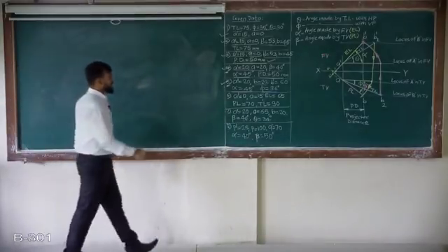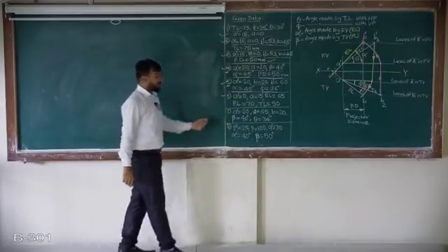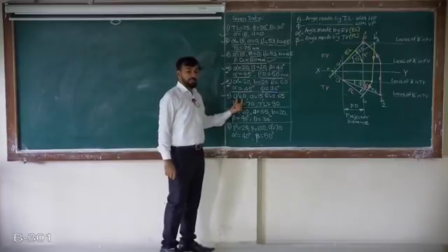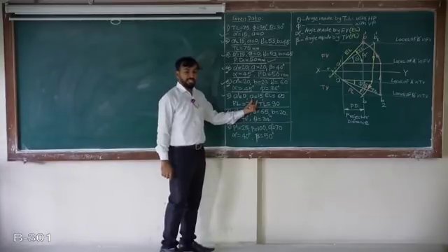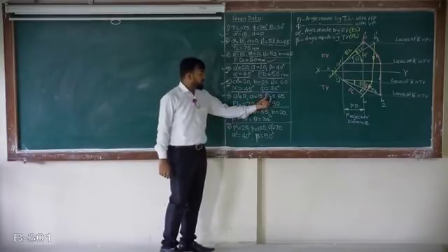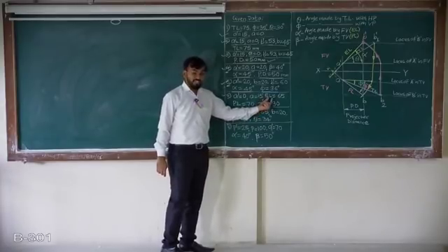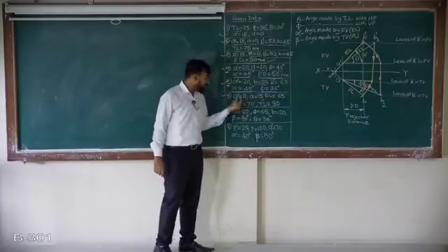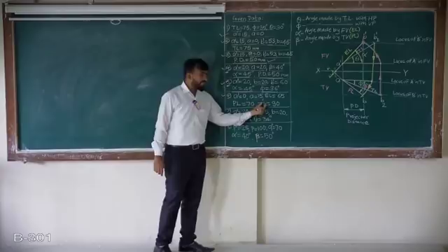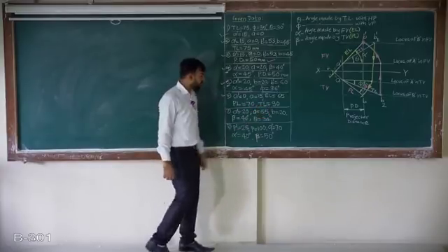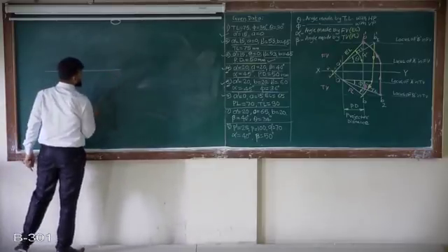Now next, question number 6. What is given? Point A dash is 0, which means point A is in HP. A is 15 mm, that means point A is 15 mm from VP. EL, PL and TL: the elevation length or front view measures 65 mm, the top view measures 70 mm, that means the plan length, and the length of the line is 90 mm, that is the true length.